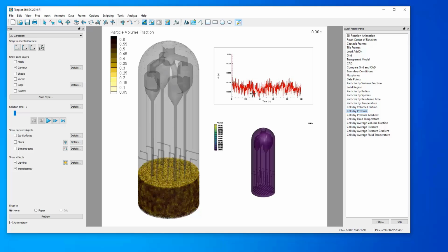That's because Tecplot loads all data being presented into active memory. With two 3D data sets being presented right now, we are doubling the memory load of Tecplot. A simpler way to do this, which is both easier and less of a memory constraint, is to instead copy any frames that originate from the same source and paste them.